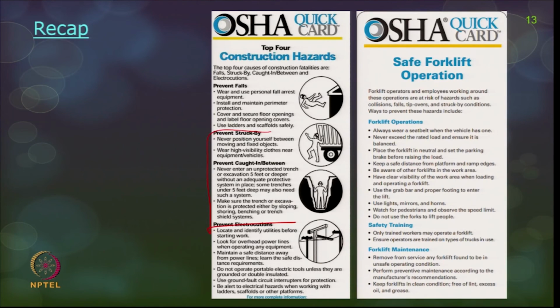Recap. We have discussed struck by and caught in between hazards. Never position yourself between moving and fixed objects. Wear high visibility clothes near equipment or vehicles so that the driver is able to see you properly. Caught in or between: never enter an unprotected trench. An unprotected trench is also one of the caught in hazards. Excavation 5 feet or deeper without an adequate protective system in place can be sloping, shielding or shoring. Some trenches under 5 feet deep may also need such a system.